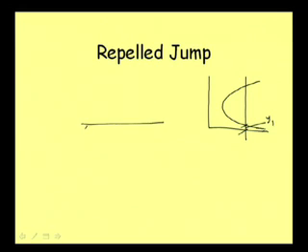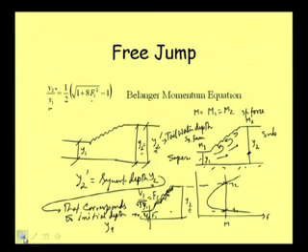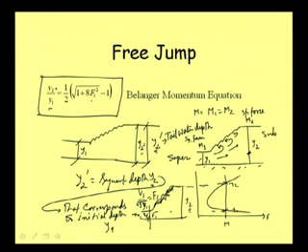or floor which is almost horizontal, and please remember one point, we should note that this relation we are talking about, Y2 by Y1, this relation is particularly for a situation when the floor is horizontal and we are talking about a rectangular channel, and for other situations there will be a different relation.